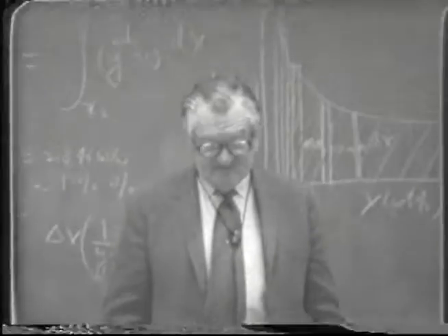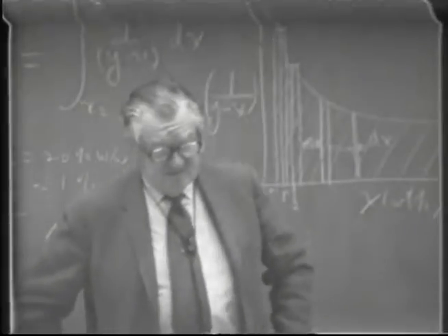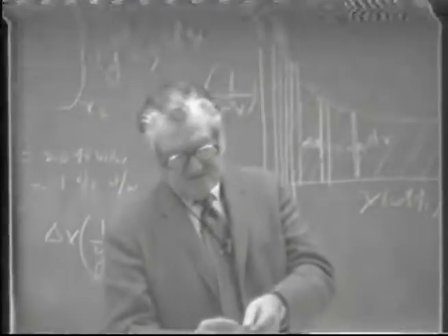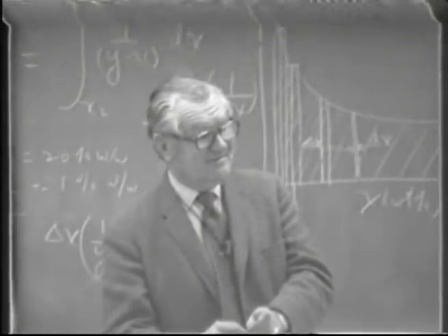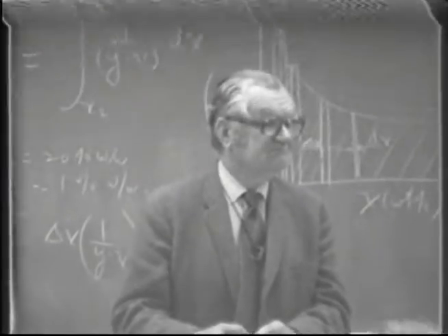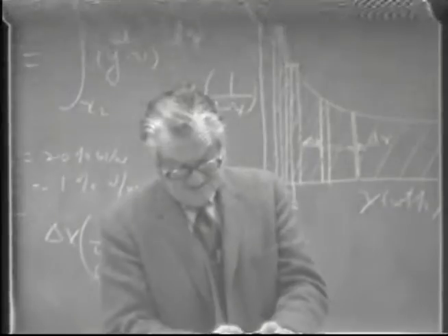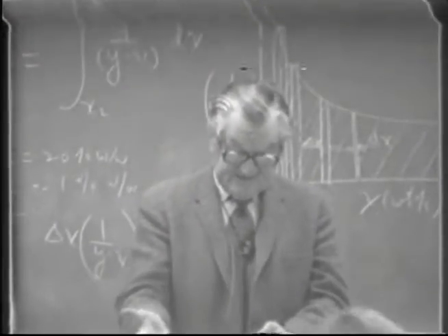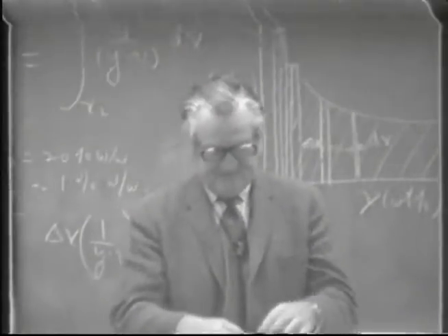And this used to be a kind of a thorny problem with the operators here in the industry, because at least if you don't have a special aldehyde concentrating column, the concentration of aldehydes in this heads cut is likely to be, or really will be, as much as 1%. Impurities will be of the order of 1% or less. Even if you include ethyl acetate along with acetaldehyde and acetal as the impurities, it may be only 1%.